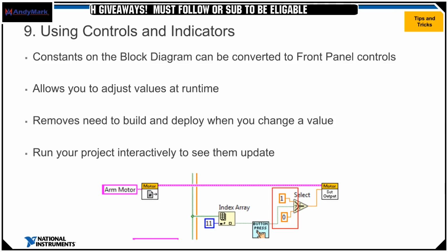Having a control versus a constant allows you to adjust values at runtime, and can help remove the need to build and deploy every time you want to change a value. If you are making an indicator or a control, you're going to want to run your project interactively. There will be a couple of additional slides in the presentation I upload to ni.com/FRC that go through how to make these into controls and indicators that show up on your front panel.